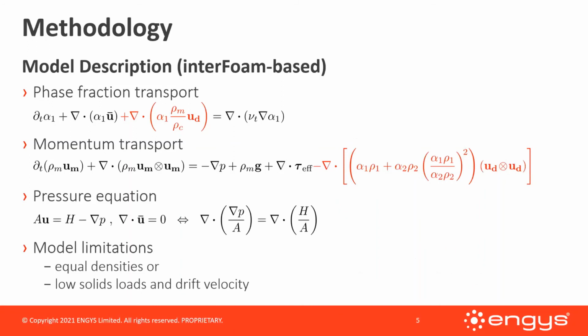So how does a drift flux-based method work? First, the numerical model and its implementation is based on the interFOAM algorithm. We see here the set of governing equations. The advection of the phase fraction has two additional terms. One is due to the additional settling flux, and the other describes turbulent dispersion. The momentum equation gets an additional drift flux term, which however is negligible in the considered range of applications. And finally, the pressure equation ensures the divergence-free field.